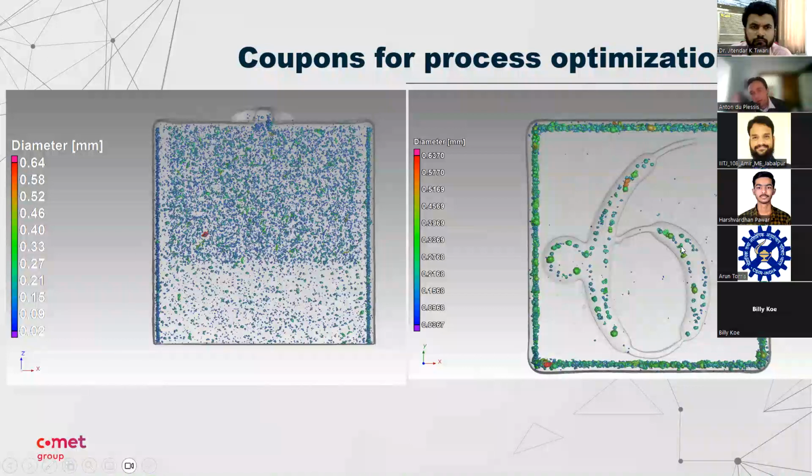And in this case, looking from the top, you see a lot of pores around the contours. These contour pores are something that occurs quite a lot, and knowing how much that occurs is important, because pores near the surface can, when there's loading taking place, when there are high stresses, cause cracks to propagate from the surface to the pore, and that can be the start of further failure.